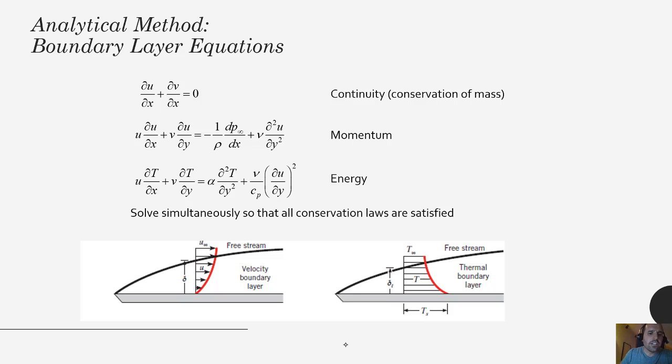What we are dealing with when we're solving for some of this information analytically, we not only have energy conservation to consider. So here is an energy balance of our system where now, because we have advection happening, we have to deal with heat transfer by advection. So we have this u, which is the velocity in the x direction, and v, which is the velocity in the y direction.